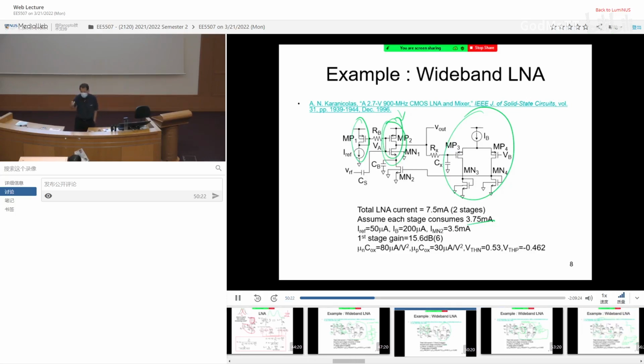Why do you give 3.5 milliampere to the main amplifier? If you are able to stay firm saying that 3.5 is a nice number, and the majority of the current consumption is in the amplifier, so I give it all to the amplifier. But who says that 3.5 is the best? Can I do it with 3? Of course, why not? How about 3.7? Why not?